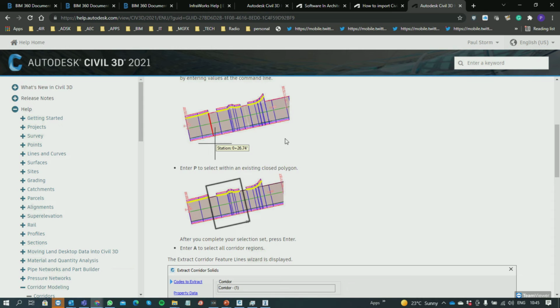you'll know if you use Civil 3D that your alignments and your corridors are essentially differential sectors along the alignment which are swept. So if you go around curves, for instance, you'll find that there are straight lines around these curves. And if you want to have a really, really good visual representation, then you might decide to generate a lot of stations to interpolate between. That'll be a lot heavier on your computer, but then it will look better within Revit. So we're not always interested in a large portion of a corridor.